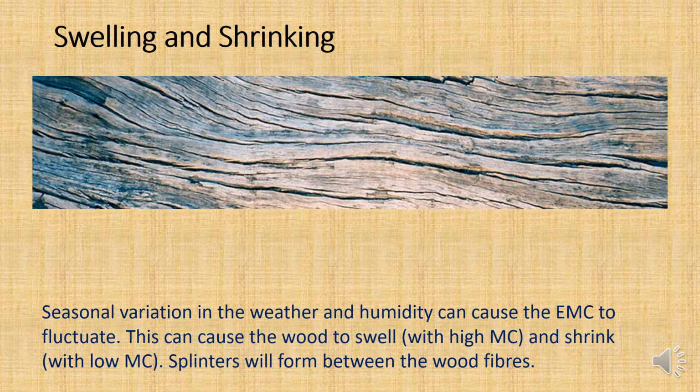No, what leads to low durability is not high moisture content, but variation in moisture content. So basically, that water that is sitting in a high moisture content wood between the cell walls, when that dries out and the wood goes to low moisture content, those 2 wood cells that are sitting next to one another are going to basically split as they're dried out.